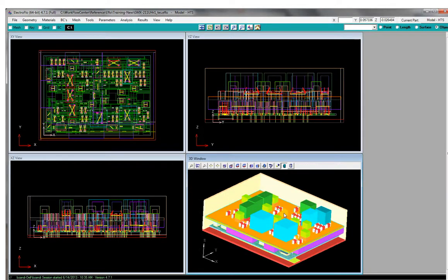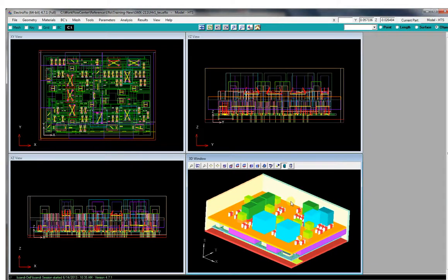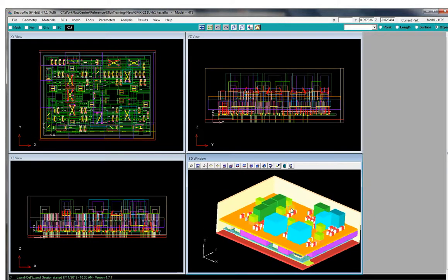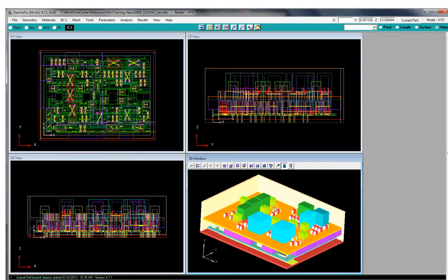For panning in 3D view, move the mouse pointer to the 3D window again and press down the Control key. Now click the mouse right button and move the mouse. Again, you could left click on the dynamic panning control, then left click on the mouse and move the mouse around.